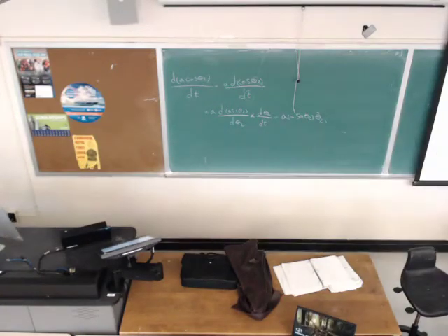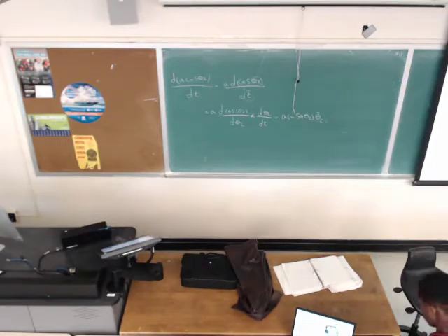So on matrix X, we are going to have the variables, which are unknowns, which are d dot and theta dot 3. First row representing the first equation. Second row representing the second equation. On this term, we are looking at the coefficient of d dot on the first equation. The coefficient of d dot is 1, we plug in 1. The coefficient of theta dot 3, it's coming here, negative b times sine of theta 3. And right hand side is going for the constant part, which is this term.